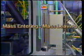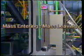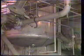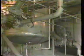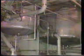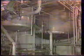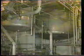One of the basic premises of fluid mechanics is that mass is a conserved quantity. The mass entering a system is equal to the mass leaving the system when both are measured over the same time interval. The simplest method for determining the rate of flow of a fluid would be to catch the fluid in a container and weigh it over a given interval of time. It is not always possible, however, to determine flow rate by weighing the fluid. An example is gases that cannot ordinarily be condensed into a liquid, or in cases where you cannot break into the system to make weight measurements, such as a closed-loop chemical process. So it's clear that the basic weight per unit of time method must be augmented by other, better-suited means.